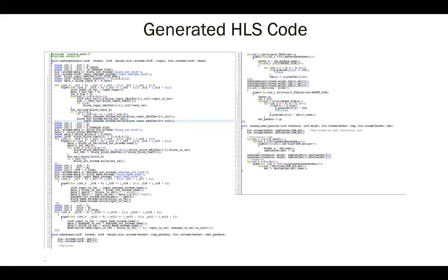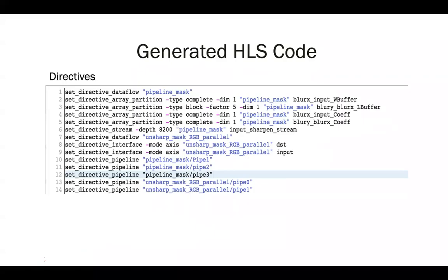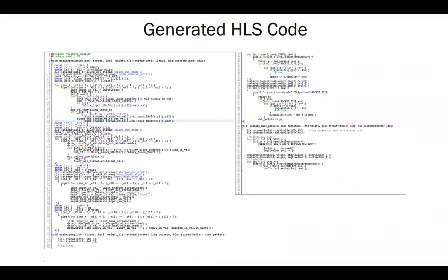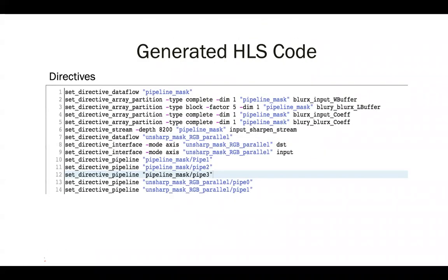And in fact, when you go for a bigger pipeline, there will be a set of directives; you can either intersperse them within the code using pragmas, or you can put them in a separate file, which tell the HLS compiler how to go about synthesizing the hardware.